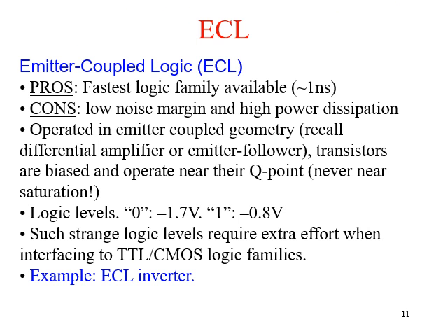Another digital logic family is the emitter coupled logic, that is ECL. It is very fast. It is the fastest logic family available, but it has low noise margin and a large power dissipation. Sometimes there are applications where power dissipation is not a consideration, but we want very fast circuits. So what we do is use the ECL series. The logic levels we use are given here, and we can design an ECL inverter here.